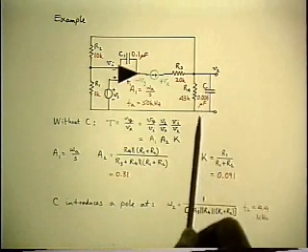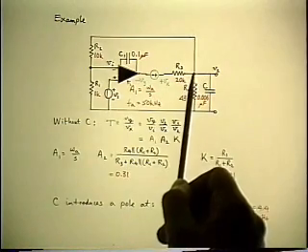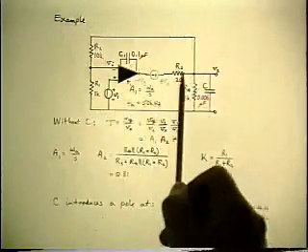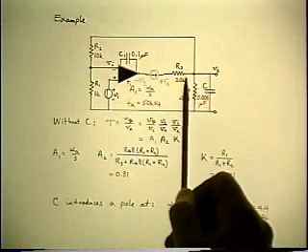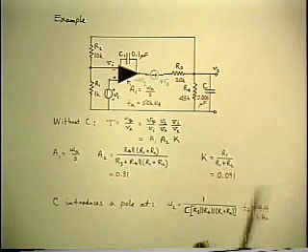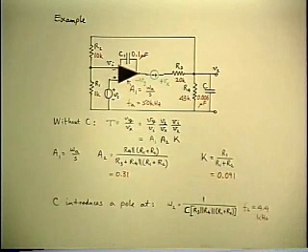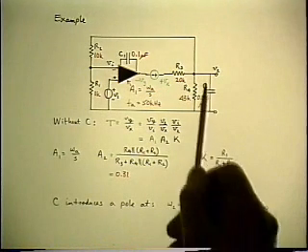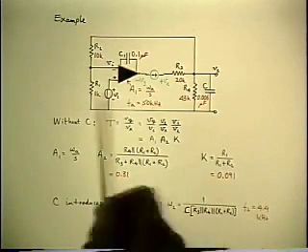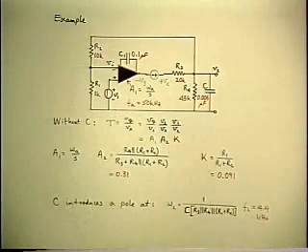Because this capacitor is right across a node through which the signal passes in determining the loop gain. So at infinite frequency, the capacitor will short the loop, and the loop gain will be 0 at infinite frequency for that reason. So the capacitor produces a pole, but it will not produce a corresponding 0, which is consistent with the detailed result that when you solve for Rn, the answer is 0.